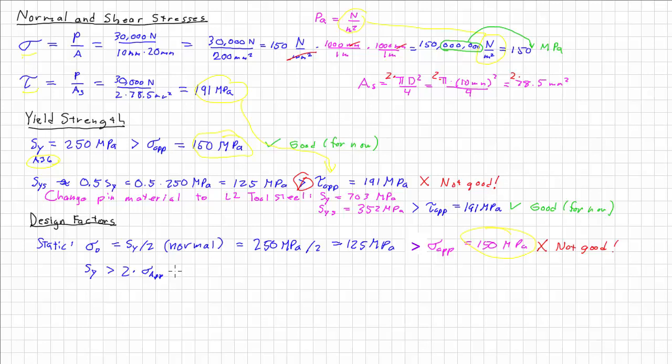And our applied stress is 150 megapascals. That means that our yield strength should be greater than 300 megapascals.